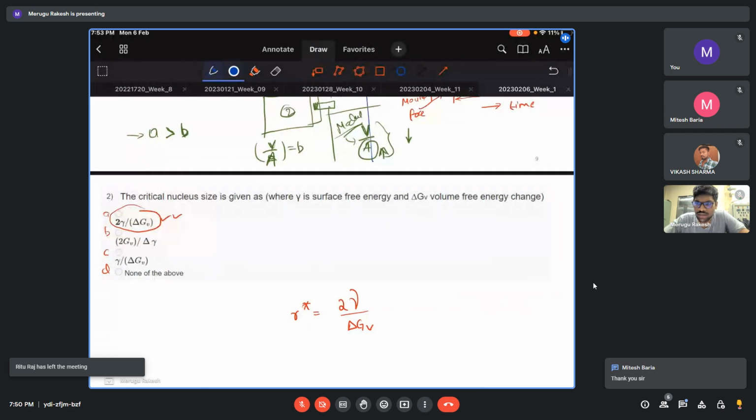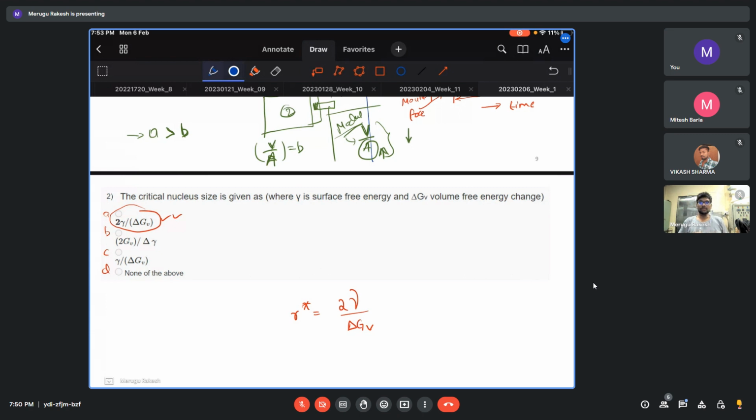I'm not quite sure about this question you are asking, but in general this is the fundamental way we look at it. Generally, for alloys we get an equiaxed structure in the center, whereas for a normal pure metal we just get columnar structure and a center line. So if I apply that to brass, which I think is a copper binary alloy, you should ideally get the alloy structure.